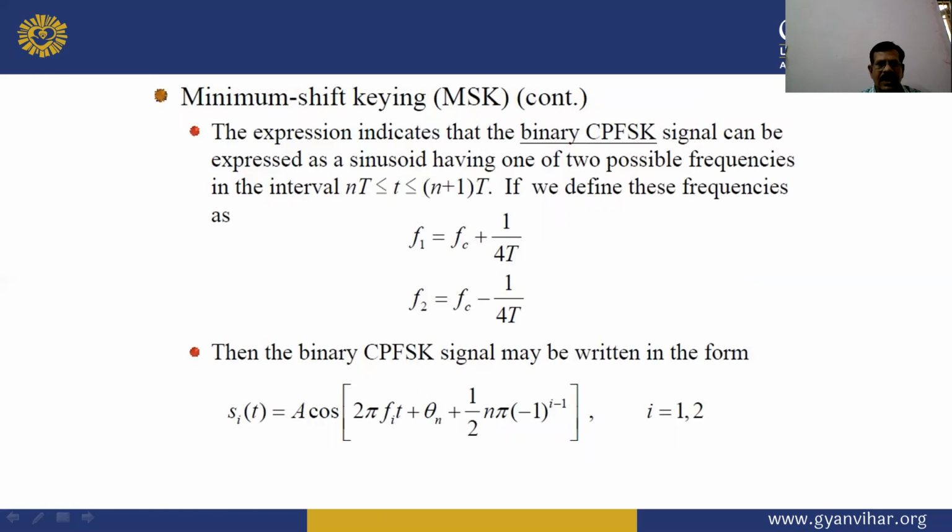The expression indicates that the binary CPFSK signal can be expressed as a sinusoid having one of two possible frequencies in the interval nT to (n+1)T.